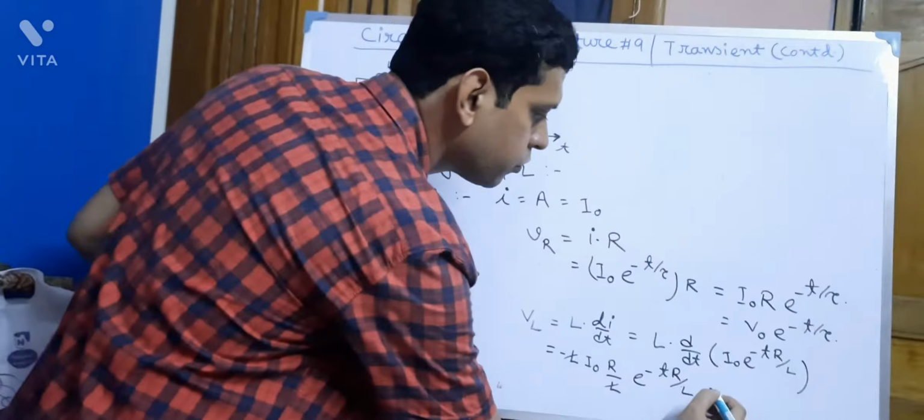One of the ways is to determine CF and PI separately, and for the complete solution of I, we add this CF and PI. This is one way of solving this equation. Now for CF, we have to solve this equation. This is nothing but the natural response of the RL series circuit.